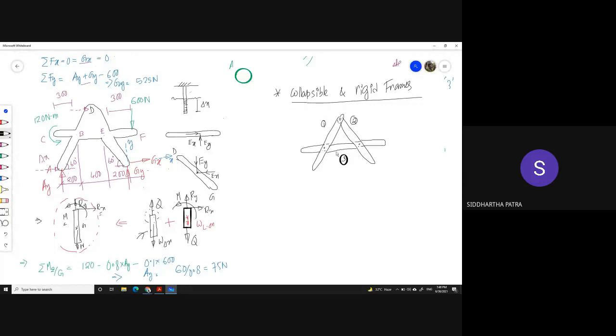In absence of member number 3, if I were to just fix one of the members, let's say member number 2, the member number 1 would have only 1 degree of freedom. It could only perform rotation about member 2. But when you take the third rigid body and you pin them with the other two, this is what happens. You see,